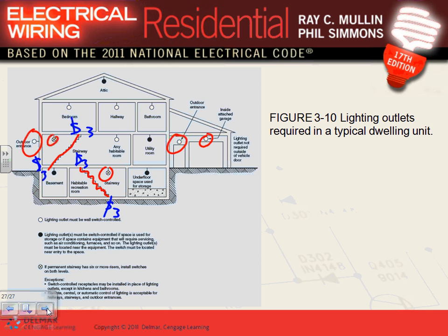Yes, sir. Switch one for the living room as well? The living room means a wall mounted switch? It can't be a pull chain in the ceiling for the living room? Yeah, you can. I wouldn't do it, but you walk into the living room and you pull a chain to turn the light on and off. You can by code. It's not a kitchen, it's not a bathroom.